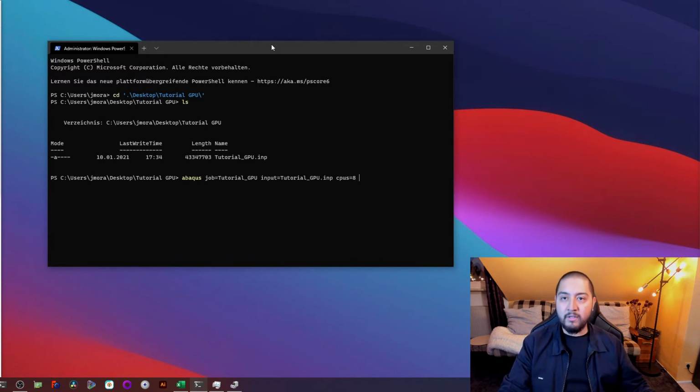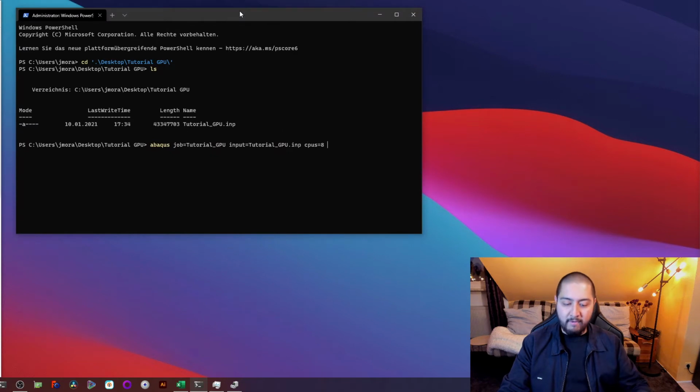And then we need to define the GPUs. This is the most important thing to activate the GPU computation capabilities of our system. We are going to define one here as an example. And then I always like to activate this command also. Sometimes if you are working locally on your computer and you are connected to the license servers, usually you are connected to license servers when you are using Abaqus, or if you are using the student license, you probably have the license installed locally.